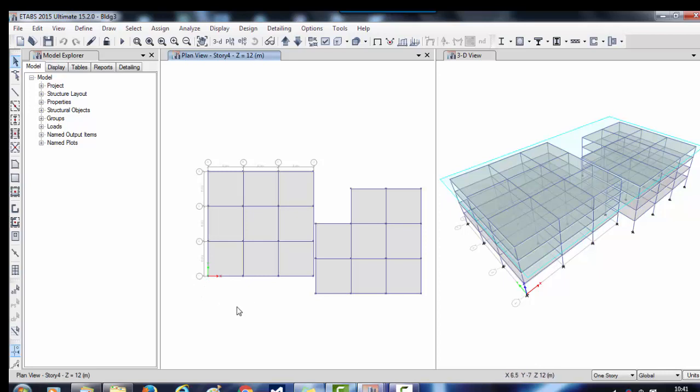This we have observed in X direction. Now observe the same thing in Y direction. So now we see that there are several different combinations of the movement of the two buildings. However, when we are having these two buildings as independently analyzed buildings separately, then we cannot combine the response spectrum results of the two models which have been analyzed separately.